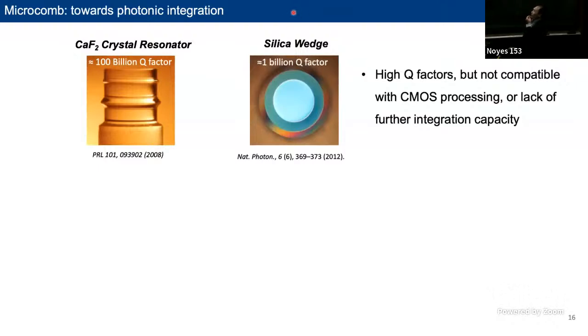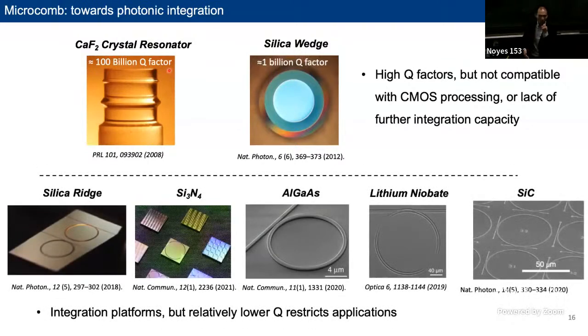The Q factor of those resonators can feature, at the state of the art, from a billion to a few hundred billion, depending on the material you are working with. One drawback is that some of those devices are integrable, but not so integratable, which limits high-yield production of those integrated photonic devices. This motivation drives people to further study other materials which can be better integrated.